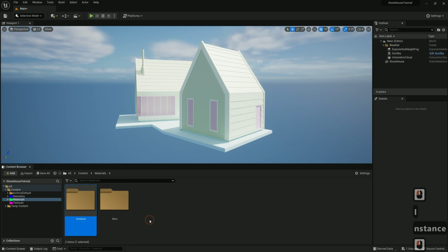Material is a parent, it contains a combination of nodes that define the characteristics of the painted surface, but any change in this material takes time to compile. Material instance is a child material that is used without such a compilation. It carries the given parameters of the parent material. Based on the parent material with a set of basic parameters, you can create many different child material instances.